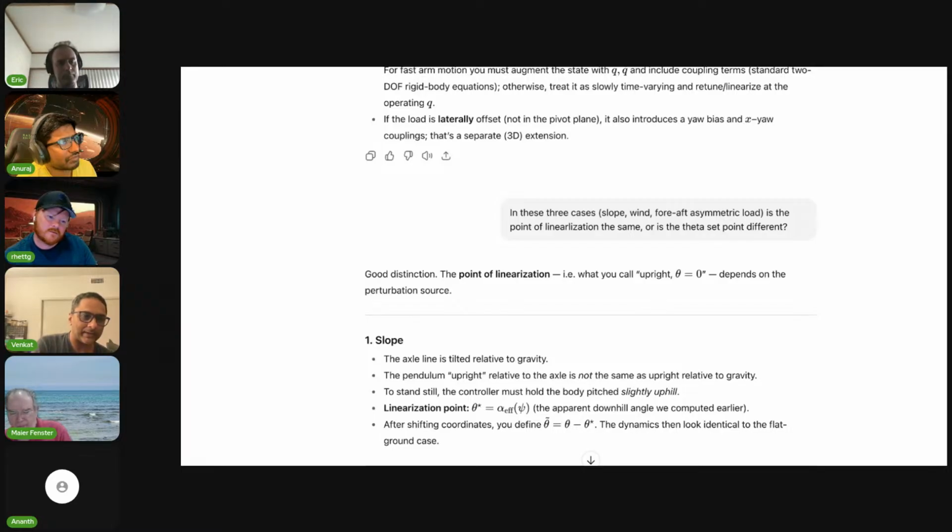It does not know that the center of mass is shifted. But if you accommodate that, redo the parameters and plug in the right modified parameters and recompute the PID gains and plug them in, then it should be able to balance, because now you'll have altered its worldview. It no longer thinks vertical is the same as the physical rod of the pendulum. It might now think vertical is off by some degrees, right? But generally at this point, you want to start moving away from a completely naive PID controller and start doing somewhat more sophisticated things. So Eligu, by the way, is there a way to autonomously detect? Yes, there is, and it's there later in the chat. So you have to start doing a little bit of adaptive control at that point.